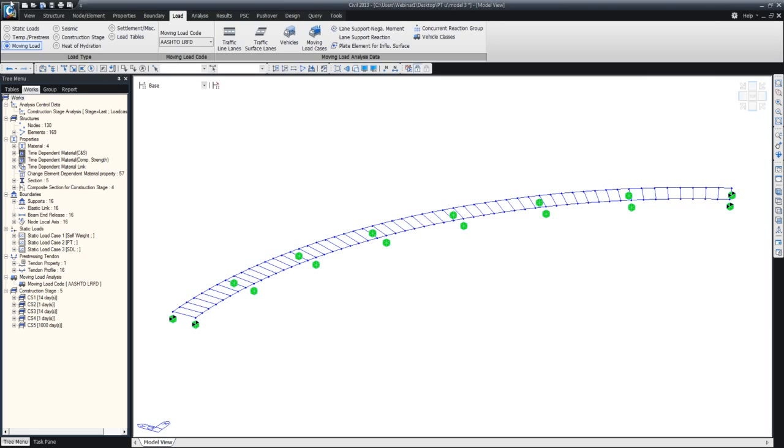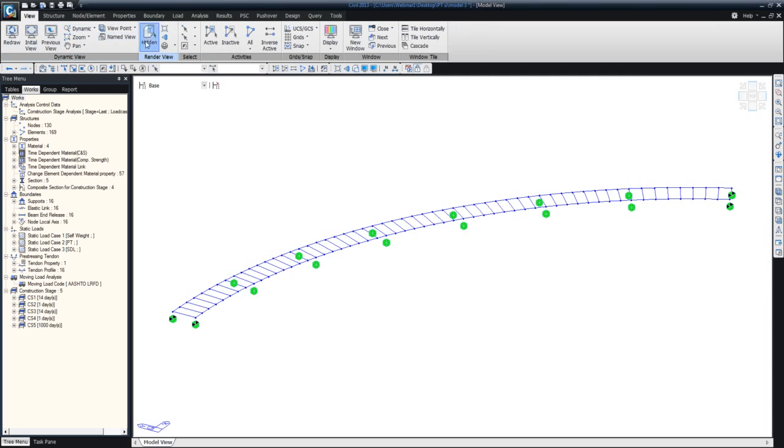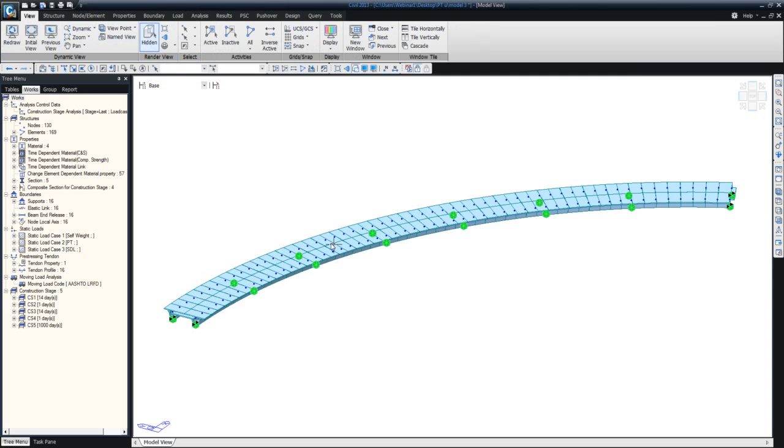So when we are saying we have the lid slab and the deck slab in the picture, we are saying that their longitudinal stiffness is taken care of, and the transverse stiffness of the deck is being represented by a transverse member.